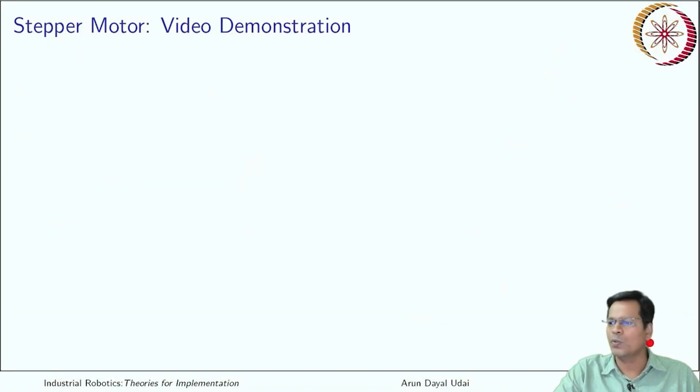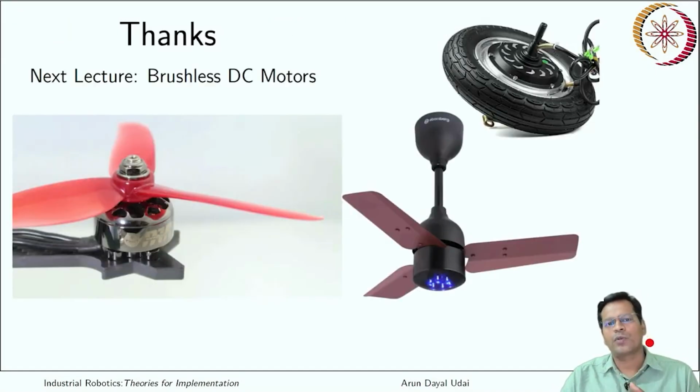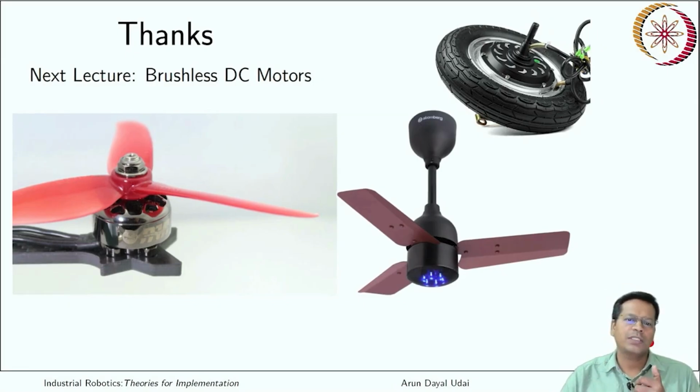So yes, now you know very well how a stepper motor can be made to run, different types of stepper motors, how they are internally connected and how they are constructed. Not in much detail for micro stepping, but you at least got the philosophy here that it is very much like a bipolar stepper motor, and you can gradually shift the pole using a current chopper drive. That's all for this class.